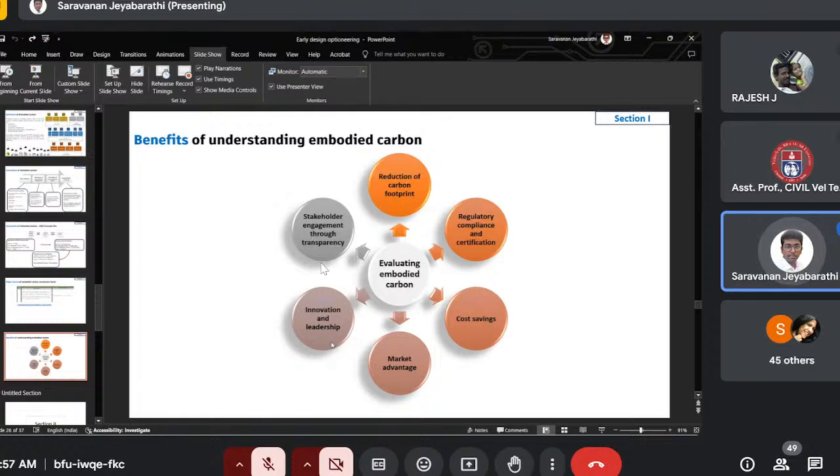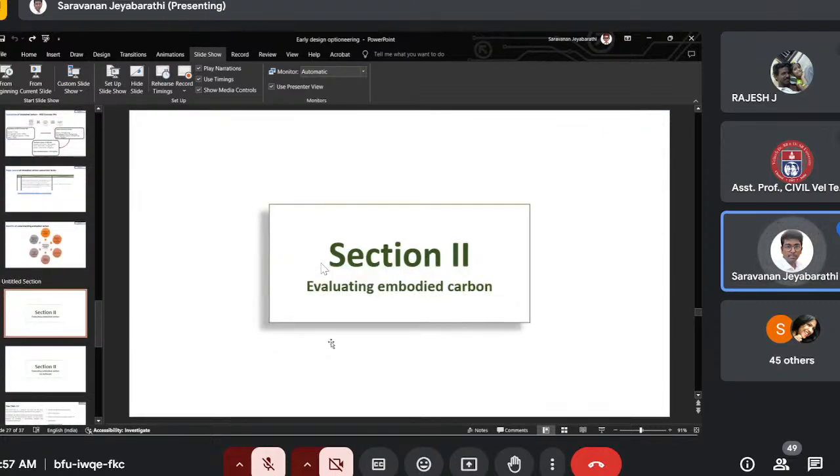So wherever you see something green, please try to look for some number, that kg of CO2 equivalent, like that. If it's not there, it is fake green, right? That's the ultimate understanding you should have. With respect to whatever product, be it steel, cement, concrete mix, or brick, you may come across vague claims. So that should be supported with proper carbon-based metrics. It is very important.